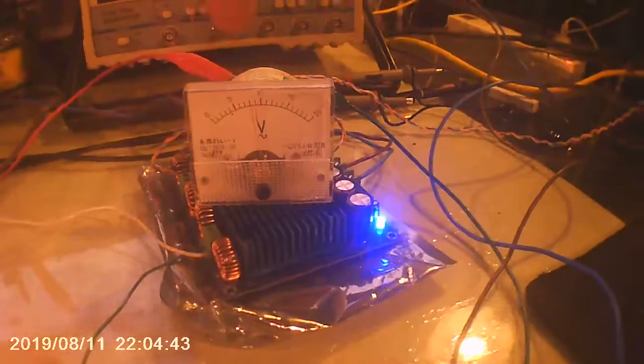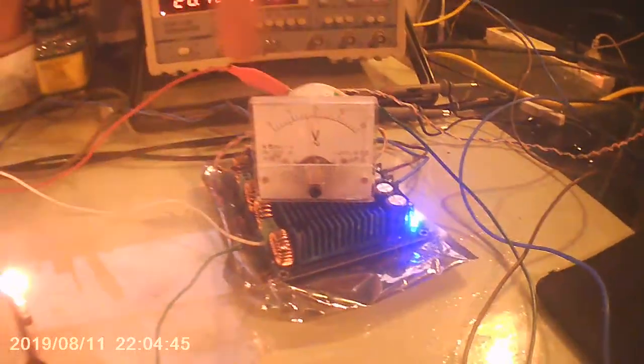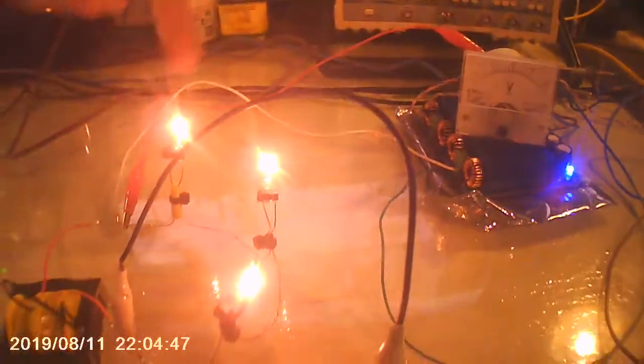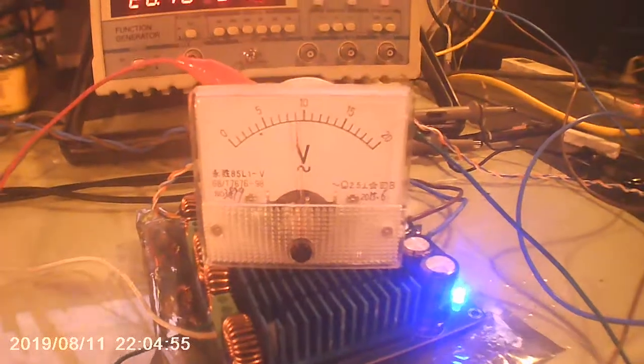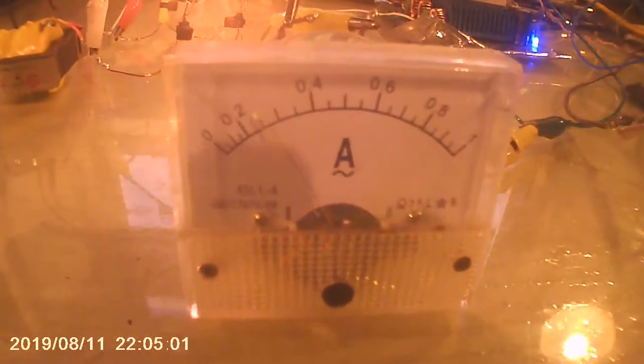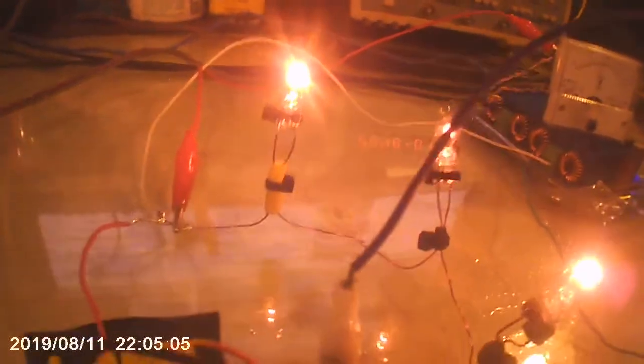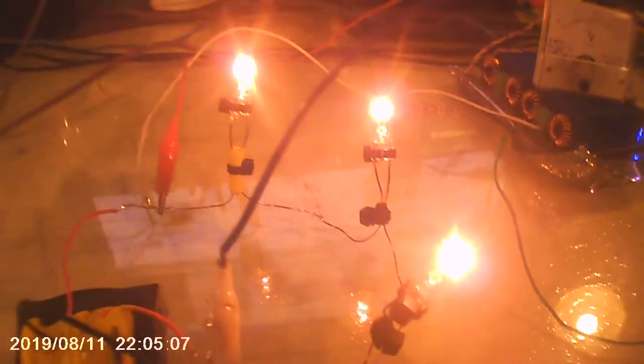But basically the voltmeter is going from one side to the other side of both the light globes and the transformer, forming the tank circuit. And these ones say 9 volts, and I've adjusted it so they look like the same brightness, 9 volts and 250 milliamps, compared to 6 volts and 250 milliamps for a single globe.